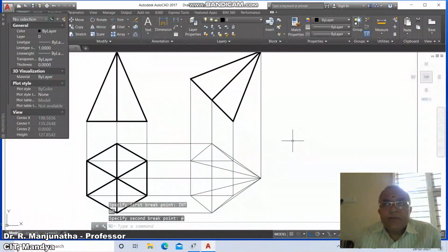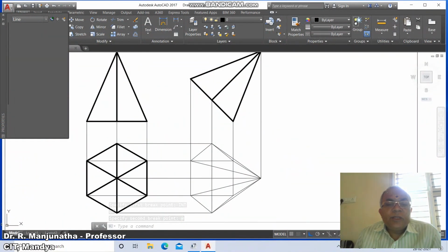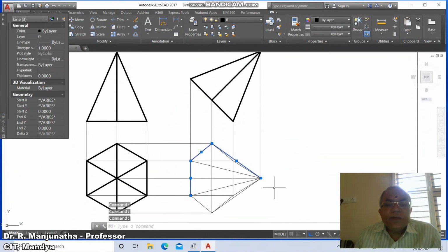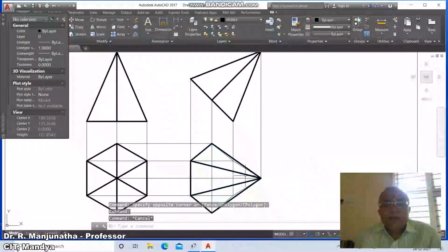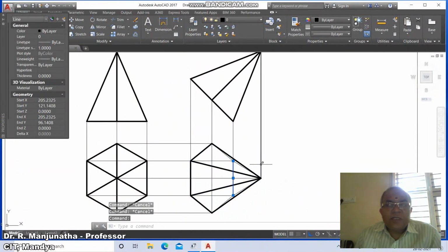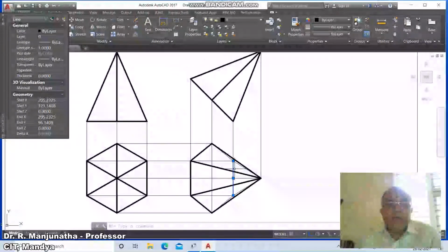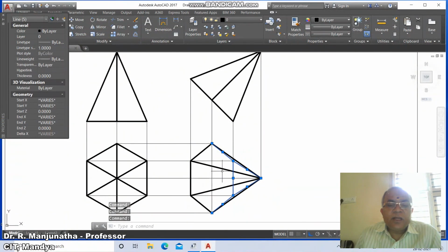So now we are going to apply the visible and invisible conditions. All the exterior edges of the boundaries of the solids are visible, and the surface near to the observer is visible, these two. So these two will become visible edges. Then the edge or a corner which is on the XY line in the front view is always invisible in the top view. Since this is invisible, then from a point, if only one of the edges is invisible, then automatically the other two edges, that is these two, and also this line and also this line, will become invisible.